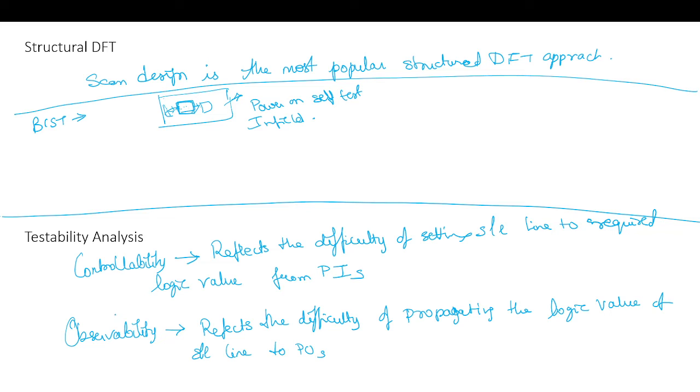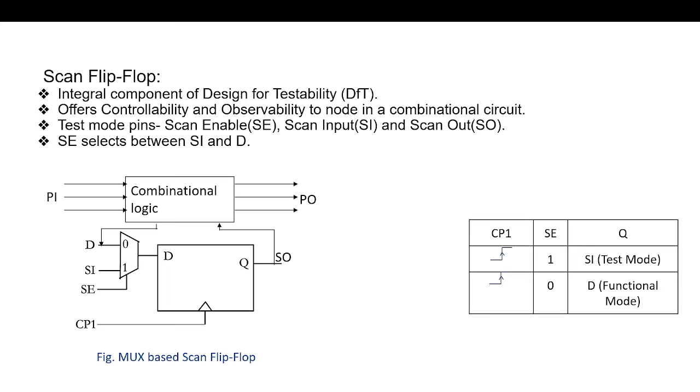In scan design, why are flip-flops converted to shift registers during testing? Okay. I think we have slides. I will discuss that. The scan flip-flops have some test mode pins which are scan enable, scan input, and scan output. So this is scan output, scan input, scan enable.